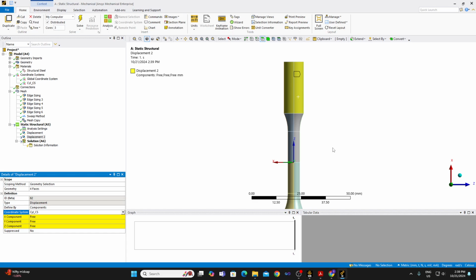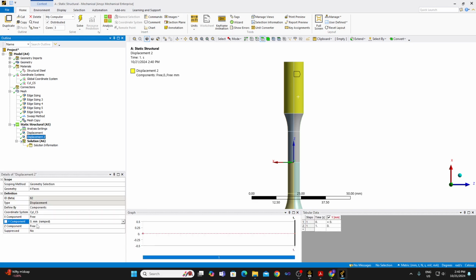So now the specimen is only constrained in the vertical direction, that is the Z axis, but it can still rotate about its own axis. So how do you prevent that? By preventing theta, which is here the Y axis. So I am just setting it to be 0. The other 2 are free. So similar to displacement 1, displacement 2, only one boundary condition is applied.